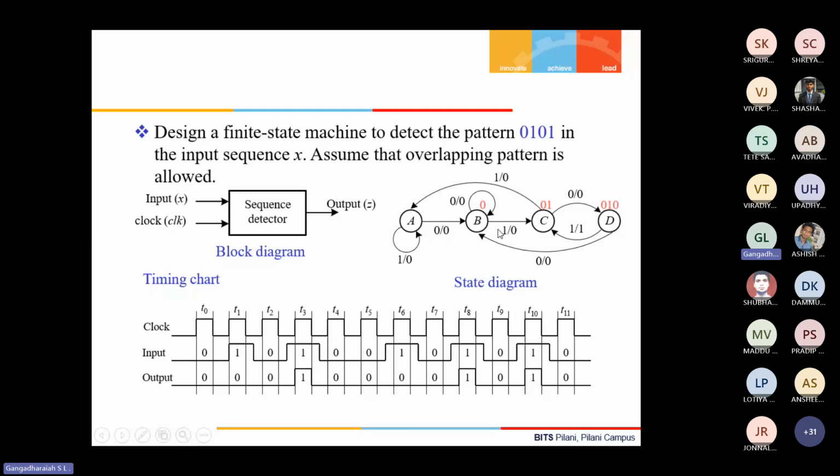Now C becomes present state, but C was my next state in the previous clock cycle. So as and when a new clock hits the system, next state always becomes present state. You should include that in one of the modeling styles, otherwise it doesn't work. You'll have to pass this information, otherwise proper transition will not happen.